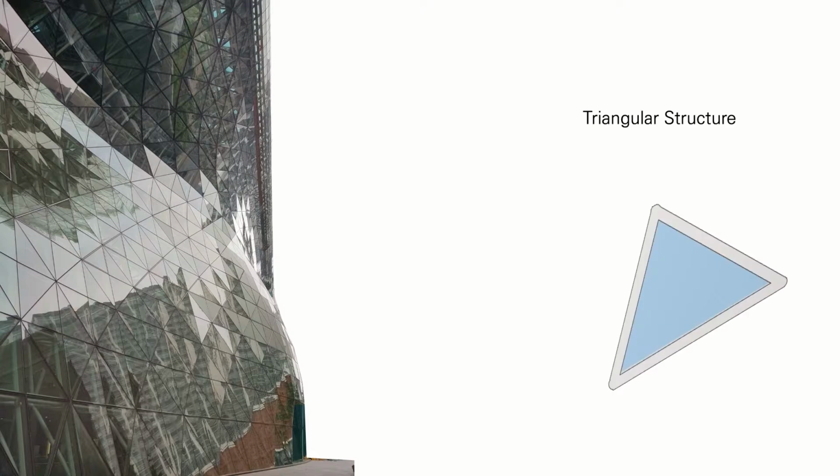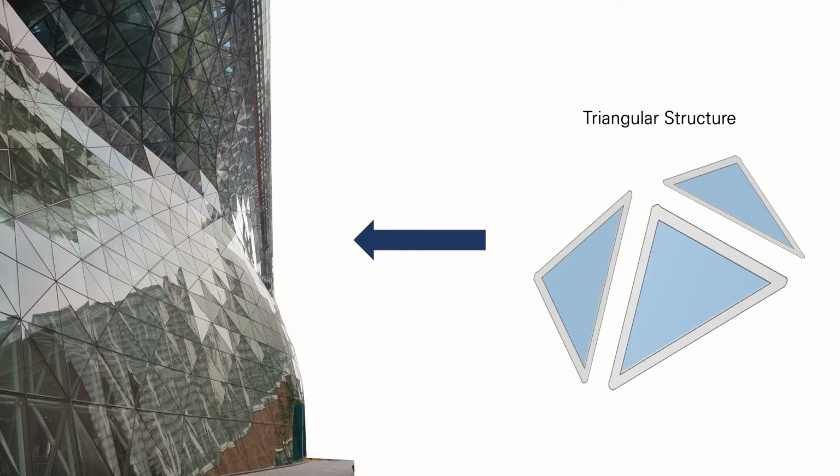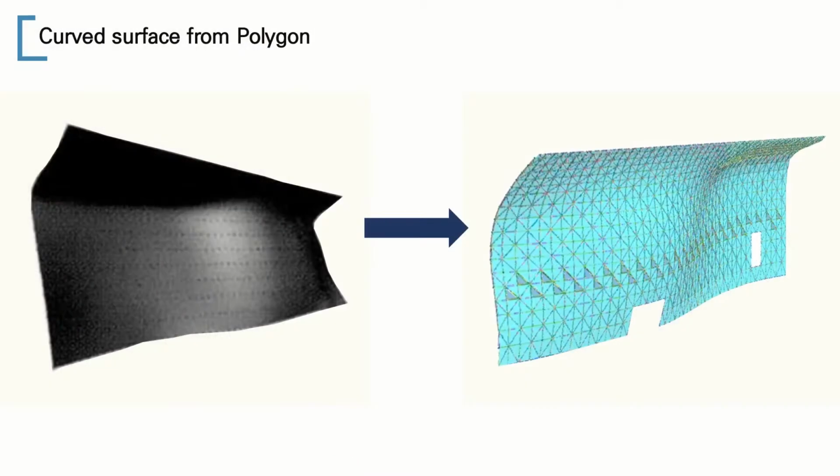First of all, if the curved surface is implemented by bending the glass, the cost and production period will increase too much, so it should be split into polygons that are flat. Because the triangle is the smallest unit of the polygons, the architects tried to express the shape by dividing the curved surface into triangles. So, how did they divide the curved surface into triangles?